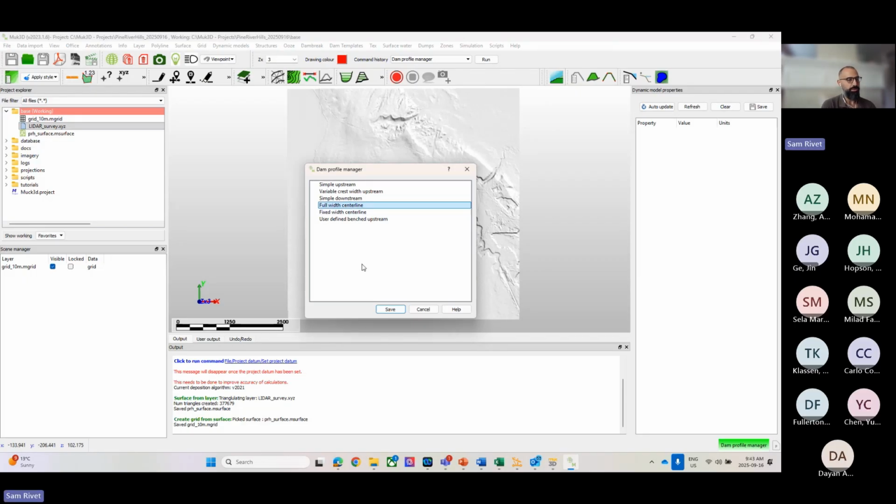I'm going to start by defining a centerline template that I want to use, which is a generic design that I want to apply to a center line in the future to allow me to build dam shells quickly without having to offset line work to different elevations. Okay, so I'm going to go to this fixed width center line. And I'm going to define a template here.